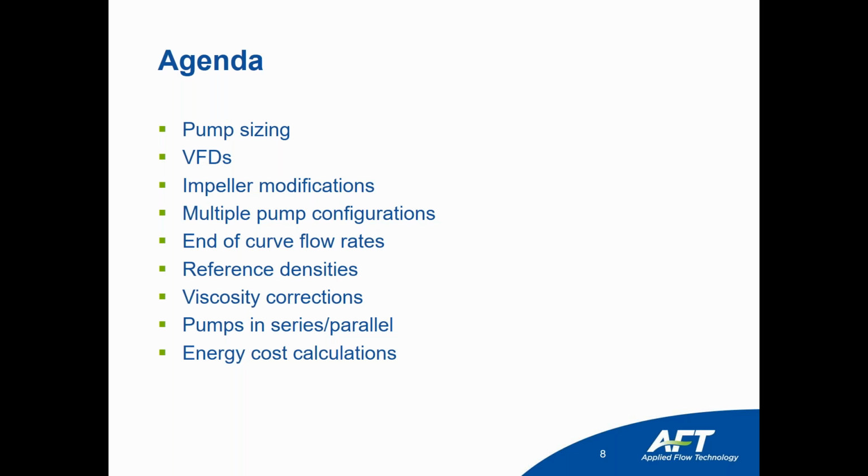I'm going to talk about the end of curve flow rates, reference densities, viscosity corrections, how you can easily model pumps in series or parallel with one pump junction, and then I'm going to do an energy cost calculation comparison where if you use a VFD, it'll help save a lot of money in comparison to using flow control valves.